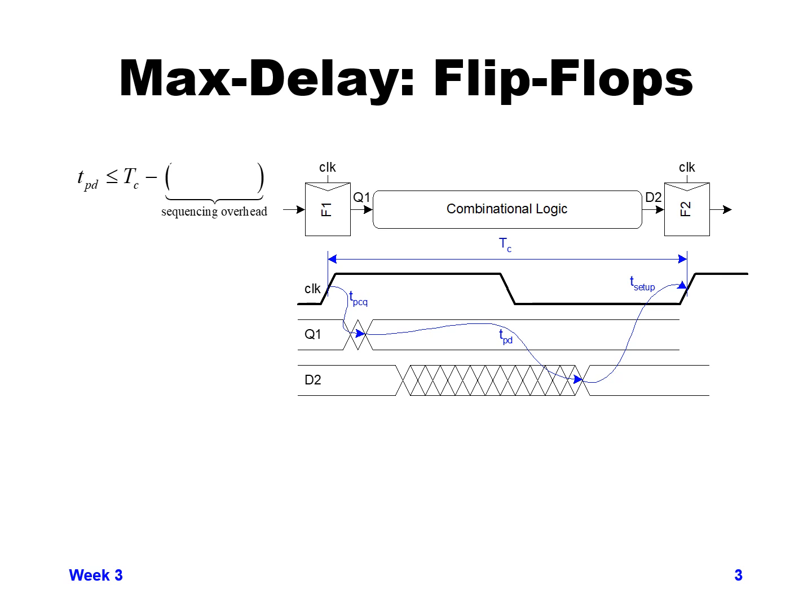In this, you can see we're trying to run at a given frequency of clock where the frequency is 1 over the period. The period in this case is the time from clock rising to the next clock edge rising, and that's large T, usually T sub C. So that's our cycle time.